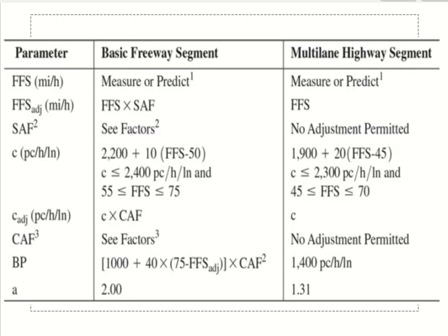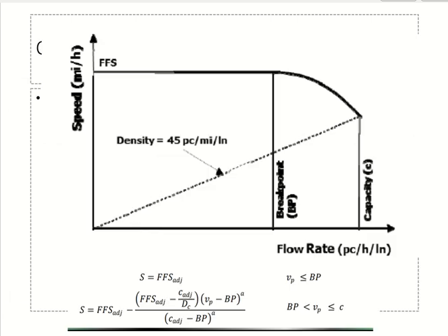Now I am drawing the curve, right? So this is the x value. I still need the y value. I need x and y both. The y value will come from this equation, which I will call my critical speed.